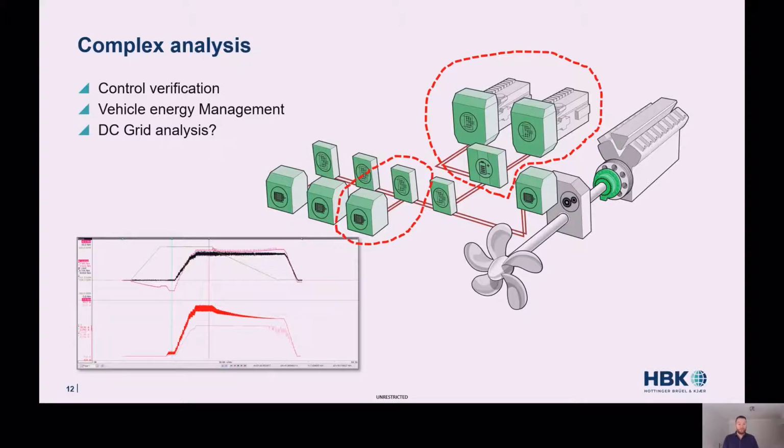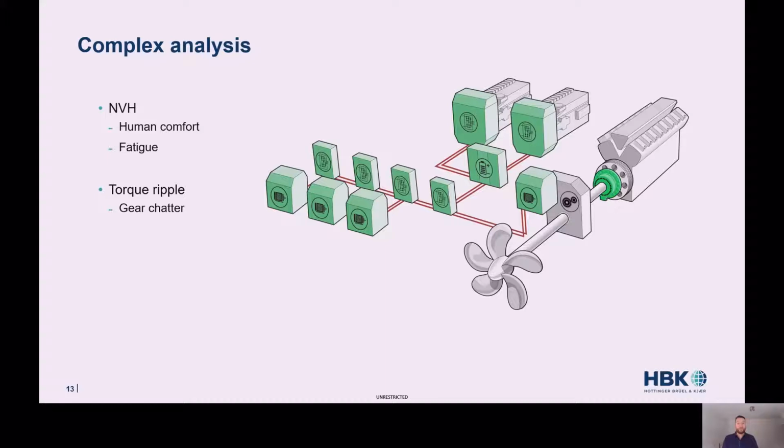And not to forget about NVH, noise vibration harshness, where also raw data plays a key role. We care about NVH for various reasons. For human comfort, for operators not being subjected to harmful vibrations and noise during the routines. For fatigue, certain levels and frequencies of vibrations can damage systems and components. Or if we look at luxury applications, it's really just all about the comfort. We look at NVH either on a system or on a component level.